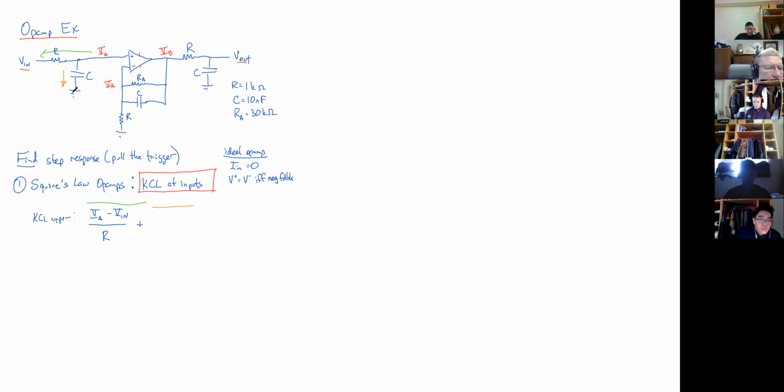How much current is going out here? Just VA over C. VA over, yeah, it should be one, except for the fact that I was a little tricky here. Remember, I did that in s-domain. It's going to be VA times SC because you flip the 1 over C. That's it.